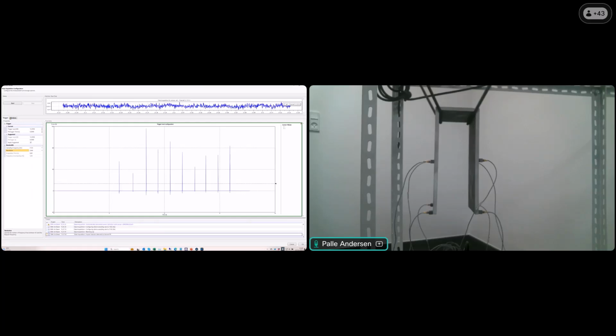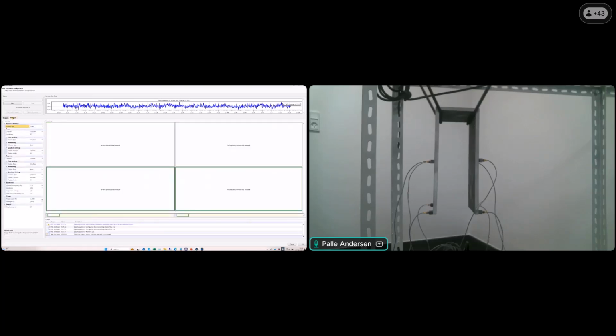Then we go to the next step, which is to see how it actually looks when we do a measurement. I normally like to see raw data and the window that I'm using. In the case of the force, I will always use a force window. The force window will allow the impact to pass, and after that it will remove any noise that might be there for the rest of the signal. There's no need to record all this noise here.